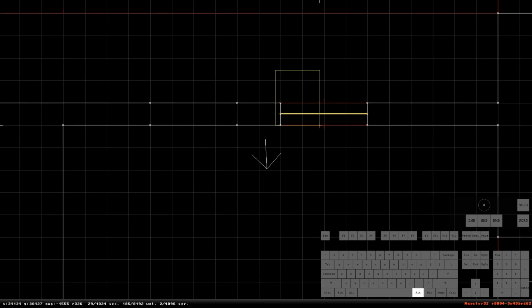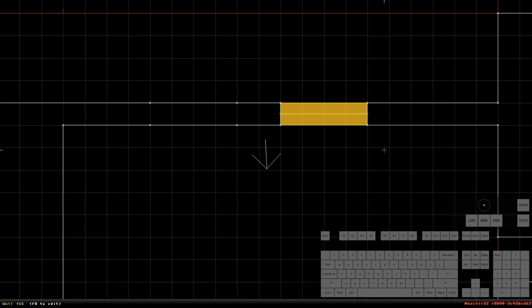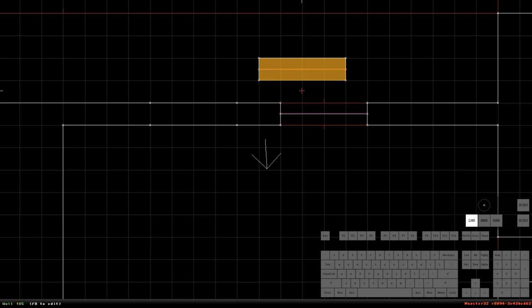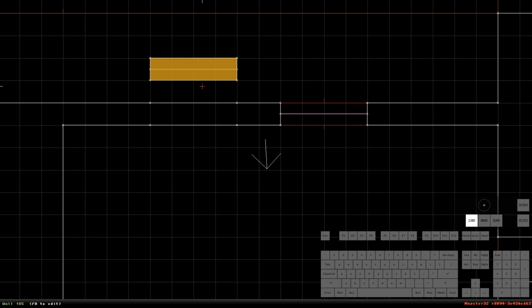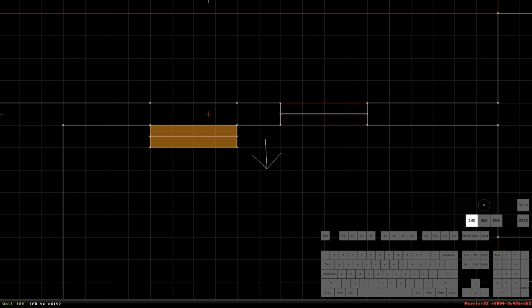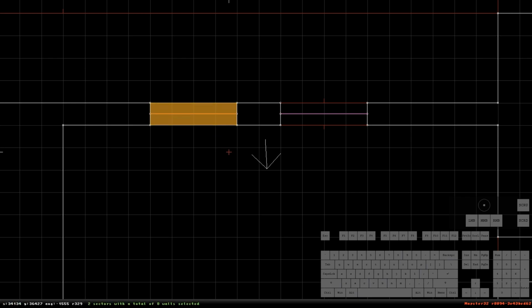Now we select the window with the sector selection. Remember, right Alt. Press the Insert key and a duplicate of our window will show up. We can move around our duplicate as we wish. Now move the duplicate to the points you created earlier. The 4 points have to coincide and match perfectly with the points of the window for this to work. If there's a perfect fit, press the right Alt key again to release the selection, and the window will be already in place.